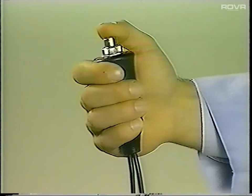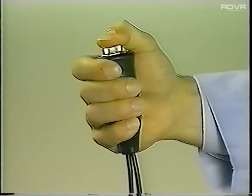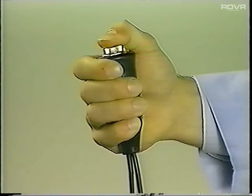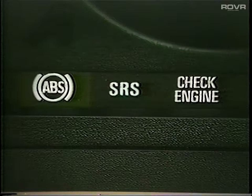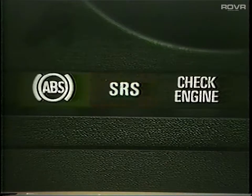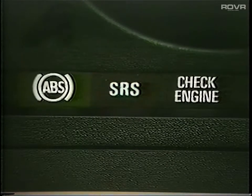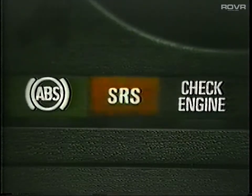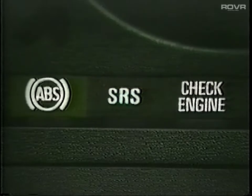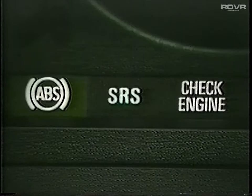Then, check to see if another fault is present by again pressing the jumper button for 2 to 4 seconds. If no other faults are present, you will see the same number of blinks again. If there is a second fault, the blinks will continue to count and stop at a higher number. Repeat the procedure until all faults are recorded.